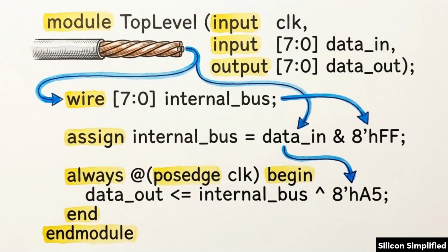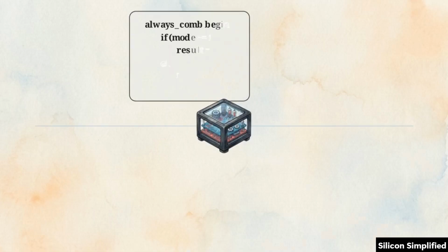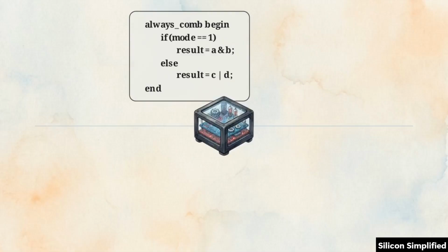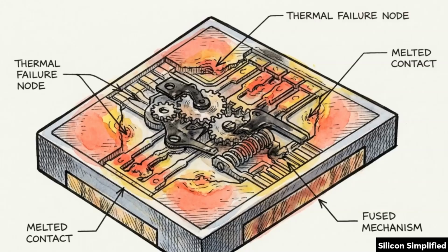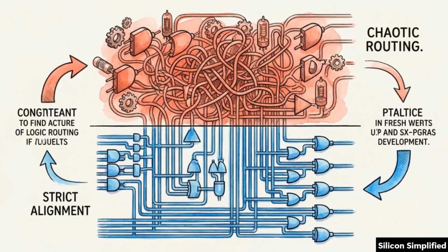It is merely a hardware description language. When we write procedural, software-like statements, a synthesis compiler must translate those abstract descriptions into a physical netlist. The compiler is forced to infer physical hardware intent based on how the designer arranges the text. If the compiler infers the wrong structure, the silicon fails. Advanced combinatorial design is therefore focused on strictly restricting that ambiguity.